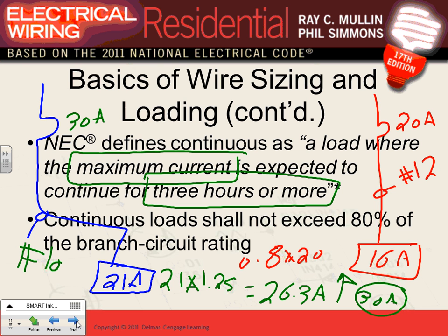If you have a circuit breaker, you derate by 20% and you find the load. If you have a load, you multiply by 25% to find the conductor and the overcurrent device. This calculation that we did on this slide, we're going to be doing a lot when it comes to commercial and industrial. That's how we're going to be sizing your continuous load. Any comments, guys, about continuous load? Does everybody understand that concept of continuous load?